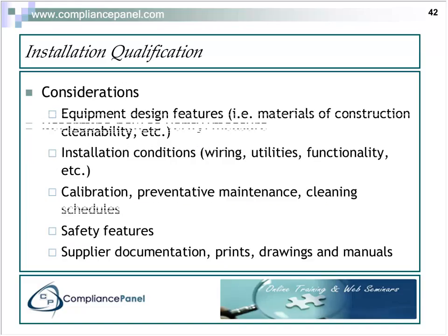We need to understand the equipment design features, how it's constructed and how it's cleaned, what kind of installation conditions apply here, the wiring, utilities, functionality, and so on. Any calibration that's required, any preventive maintenance required, cleaning schedule required, and we need to set all those up in this phase so that we have the proper maintenance, cleaning, and so on. Any safety features that prevent the operator from being injured, for instance. And the documentation, prints, drawings, and manuals that accompany it needs to be available to people performing IQ.